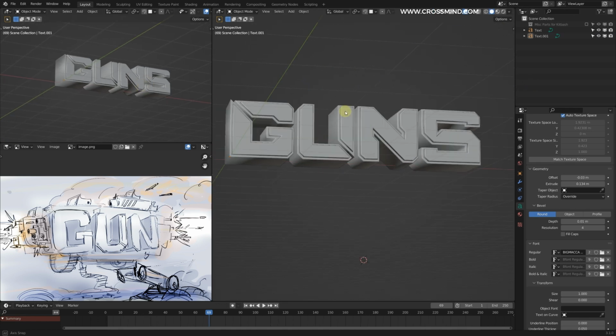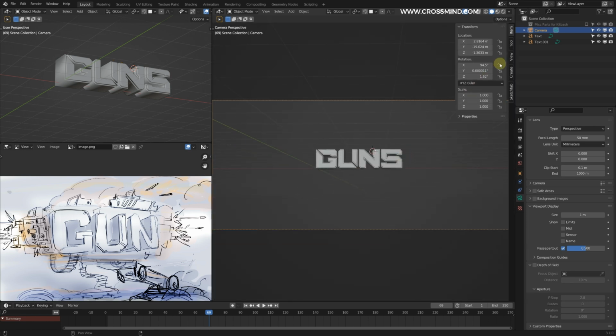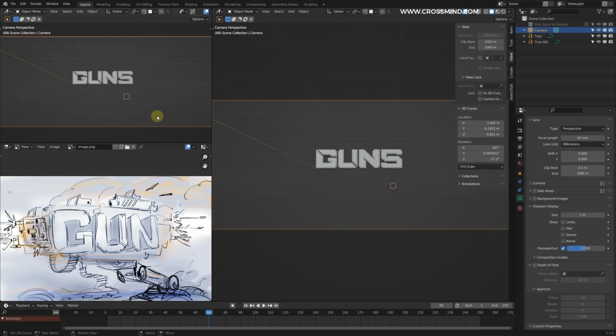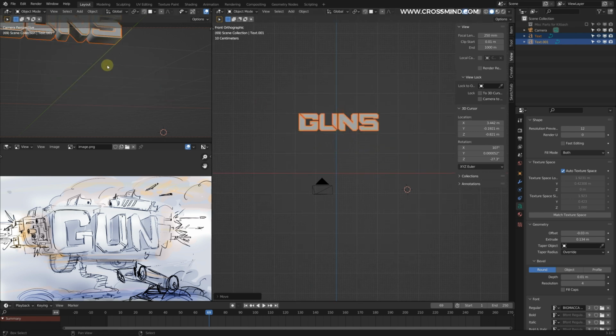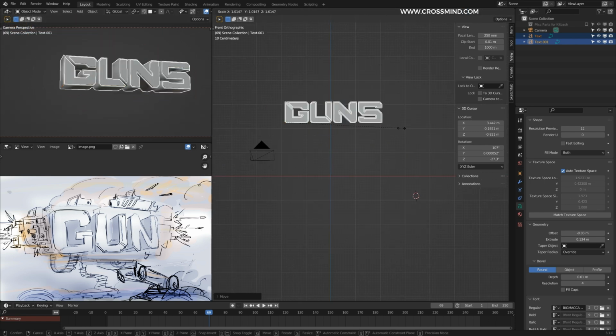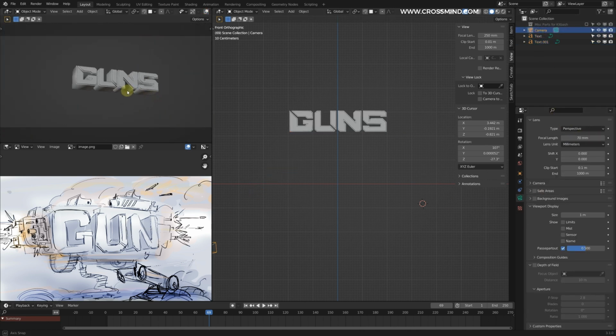The first thing I'm going to do is add one camera here. View, camera to view, and place this a bit above the ground in case we are running a few simulations. 70 mm in the focal length. I think something like this should be fine. This is set on the height, and we'll see some of the bottom part and the left part. This way we are now locked into the camera, and any effort that we make, we are going to make according to this view.